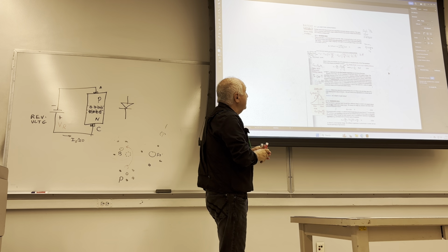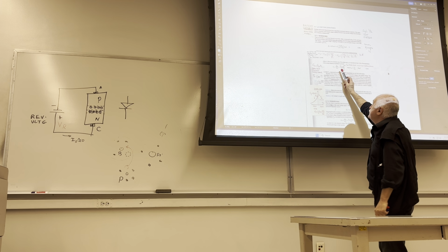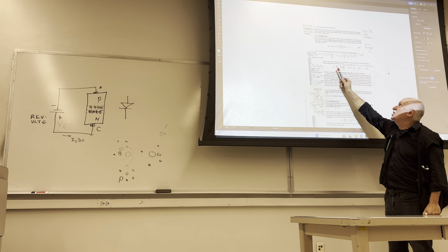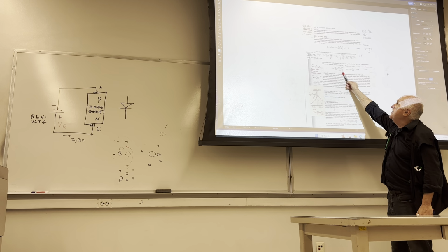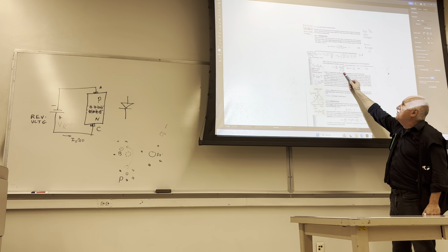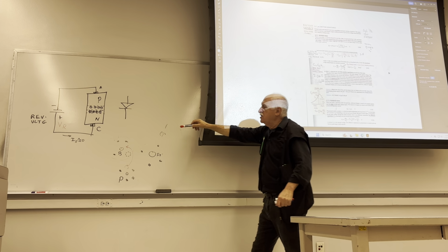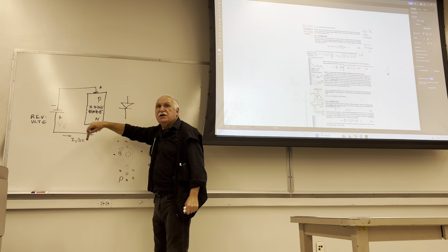The profile that it is changing is shown with this equation. That's the measure known as the junction capacitance. It only works for the reverse situation. So VR is a reverse voltage. Phi J is a junction potential, which applies to the junction between these two particular P and N materials.